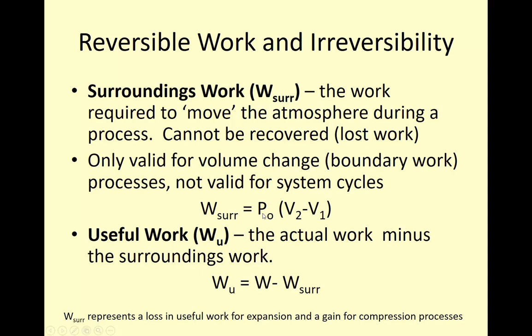Now, this surroundings work is only valid for a volume change process because it's a boundary work phenomenon. And it's not valid for system cycles because a cycle would presumably return to the initial volume, so the net change in volume would be 0. So the surroundings work is equal to the pressure of the dead state multiplied by the change in volume of our system as it goes from state 1 to state 2.